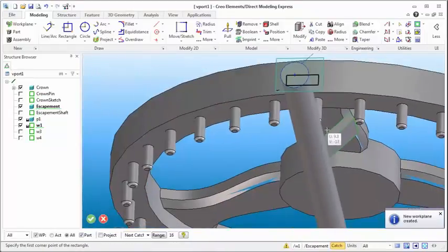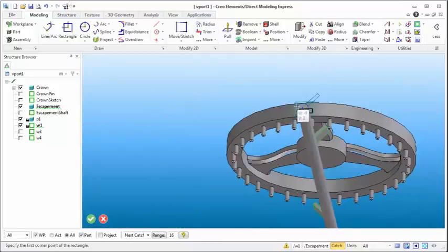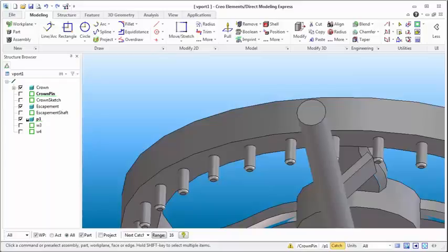we'll start extruding. Small problem here is that you'll notice that these green lines on this escapement means that this is now the active part. So anything I build is going to be part of that active part, and I don't want that to happen. And that just becomes frustrating. So I'm just going to escape out everything. Now we're in part one.